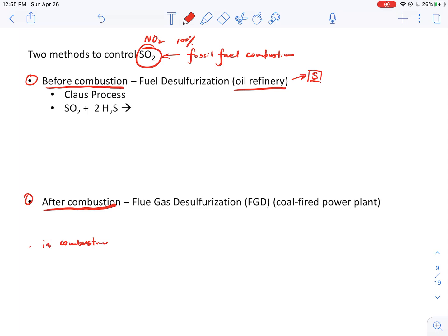So before 1970, a major thing they do is actually first convert those sulfur that's bonded with the hydrocarbons. For example, we can have some hydrocarbon that's bonded with the sulfur here. So they can use some techniques to convert this organics into hydrogen sulfide. Okay, so basically you can use the hydrogen, and then what's going to happen is that you can introduce hydrogen here, and then under certain temperature, right? Under high temperature, high pressure, you can convert these sulfur-containing fuels into hydrogen sulfide.